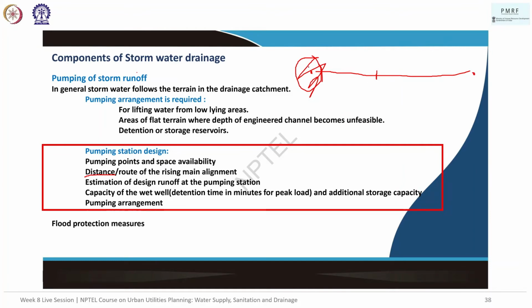Once more sewage comes in, flow might be good, but siltation might increase. So to avoid siltation, and also if the route has some sort of bend, at these points or somewhere right before it, we have a pumping station to boost the flow. You push it ahead. So that is why we consider distance and route also.